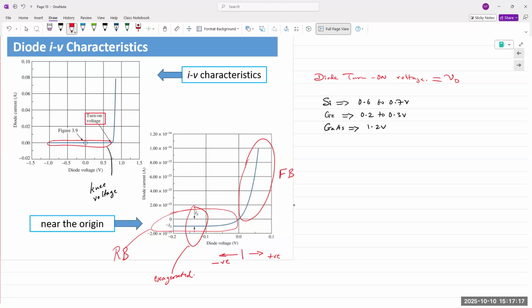And that is also something we would have observed when we did sweep and go reverse bias and we zoomed into the characteristic. It began at 0. And also in the PSpice lab, where we simulated and put it on the log scale, you would have seen the current on the y-axis was compressed scale, and so you were able to see it pass through the origin. Okay.